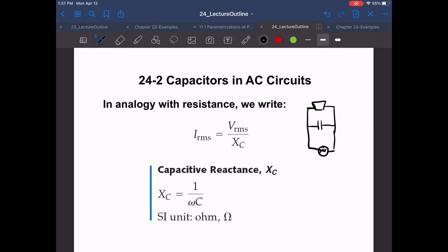Coming from my radio I'll have high frequency signals and low frequency signals, depending on what sound it is. The low frequency signals are the low sounds you want to go to the subwoofer. The high frequency signals are the ones you don't want going to your subwoofer, because they're the high pitch sounds. Well, the high frequency signals see this capacitor as a short, and they see the speaker as a resistor. So they're going to go this way, cutting through that capacitor.